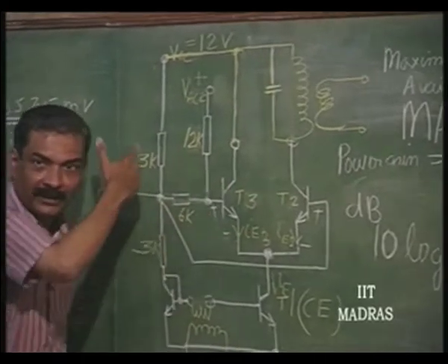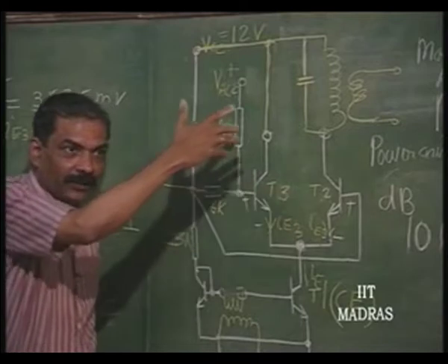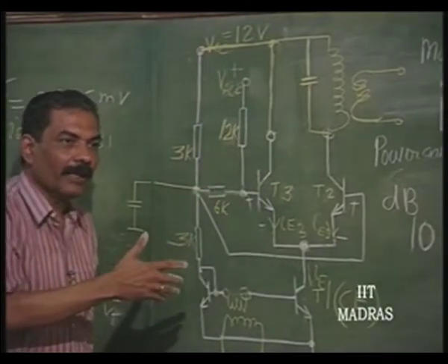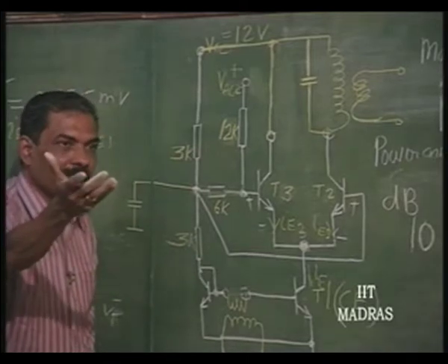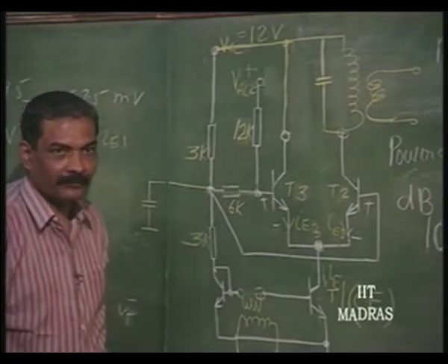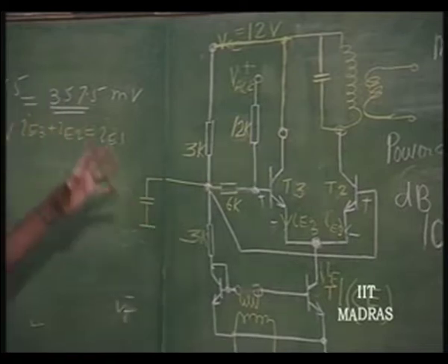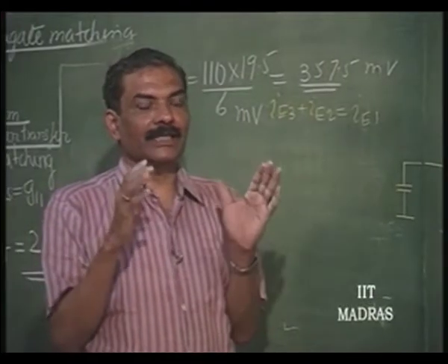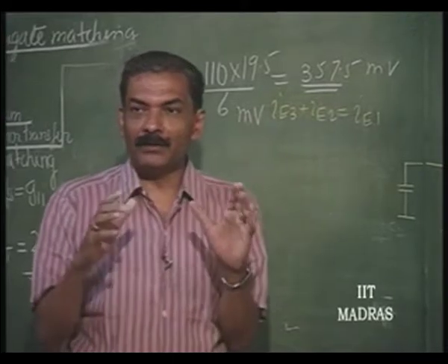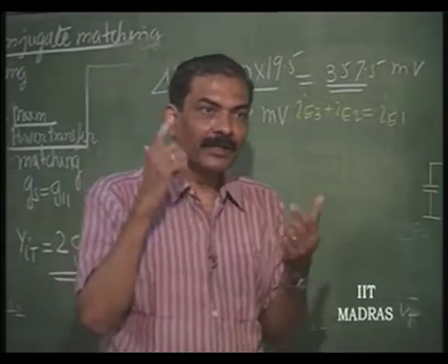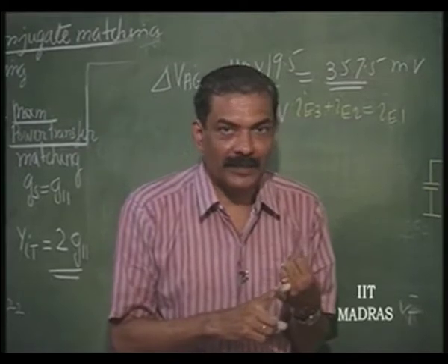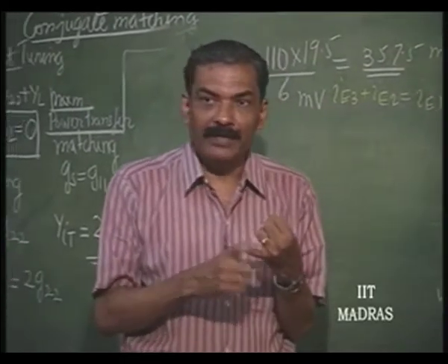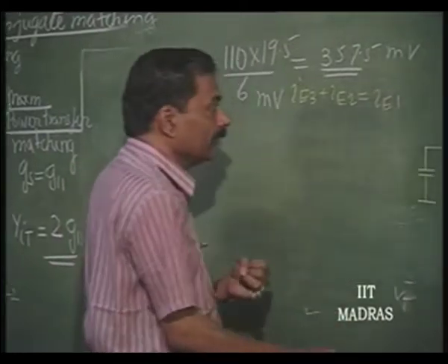If there is a communication receiver, that is fed to the RF stage also and also to the mixer. So, all these gains are controlled by the DC that is obtained at the detector. So, that is why it is called automatic gain control. So, your circuit functions very satisfactorily without this irritation about fading only when your AGC is functioning satisfactorily. This is also called automatic volume control, AVC or AGC.